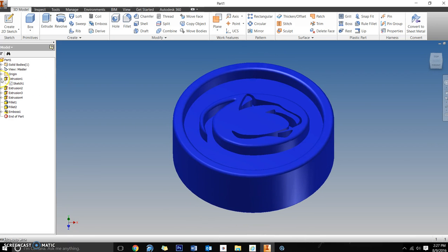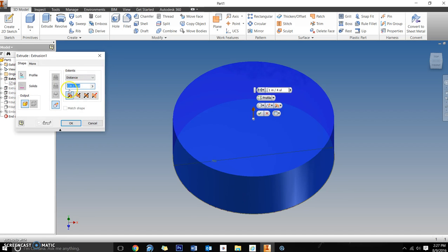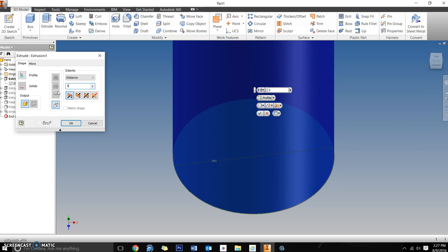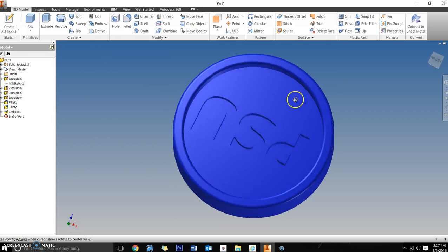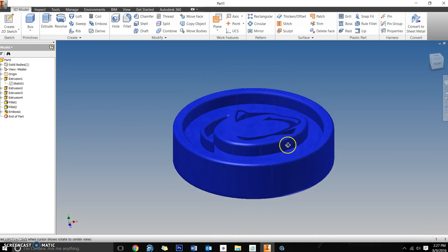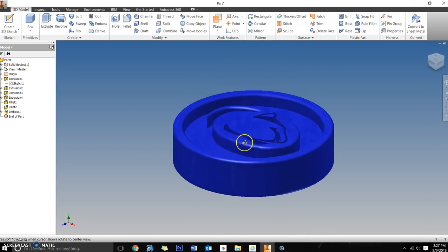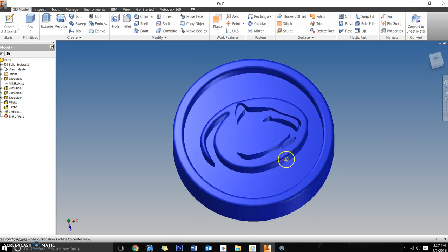I could go back into sketch 1, our original sketch. I think we extruded that a 1/4. Let's say I'm looking at it now and I'm like, you know what, a 1/4 might be too large. What if I made this 3/16? Okay, so I could take a look at what 3/16 looks like, and that looks really sharp. I think that thinner piece would work pretty well.